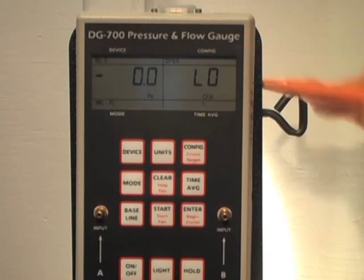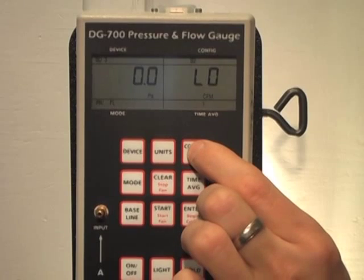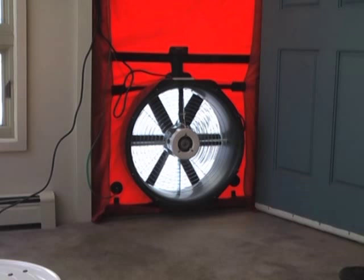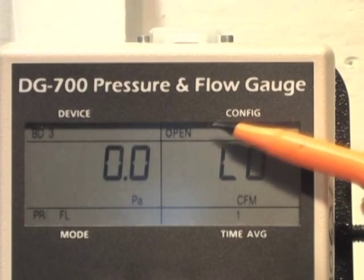Configuration is adjusted by pressing the configuration button. As with other buttons, you can toggle through the settings to find the appropriate one for your situation. Configuration refers to the configuration of the fan. Is the fan open, meaning are all the covers off, or is it set up with flow ring A, flow ring B, etc.? The default setting on the DG-700 is open.